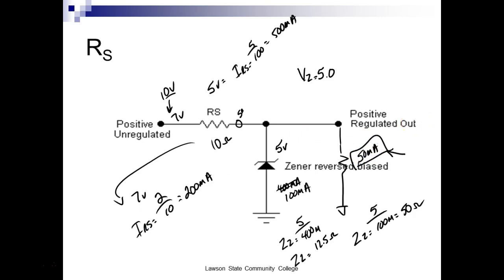So guys, what's happening? Well, we need 50 milliamps right there. We got 200 milliamps right here. We need 50 milliamps right there. Kirchhoff's law says the sums of these currents have to equal each other, right? So you see my Zener current is going to go up to 150 milliamps. Automatically, you don't have to do anything, right? You understand? You don't have to do anything.